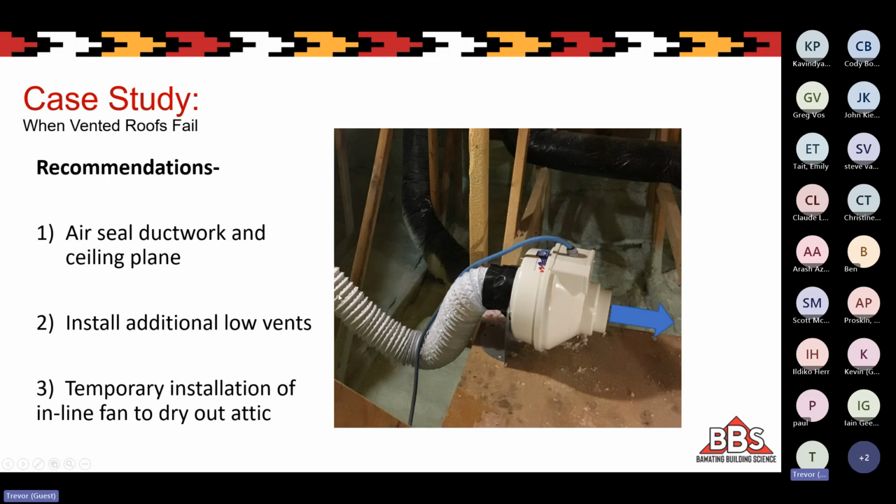And this inline fan is drawing cold air from outside and power venting it into the attic to pressurize it with cold air from outside, whereas before it was being pressurized with warm, moist air from inside. And that was done temporarily to dry it out in the meantime. And so once it was dried out, this was removed. We rechecked all of the air tightness improvements and that they added the low vents. And so far, there have been no issues since that was accomplished.